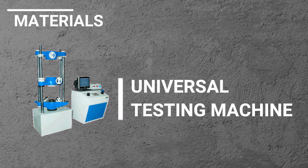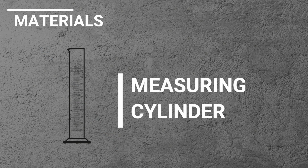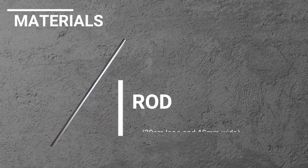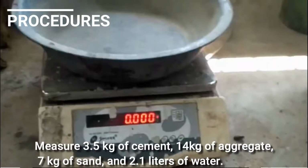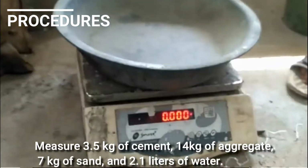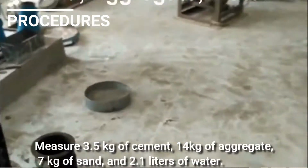The materials needed are the universal testing machine, cylindrical molds, specifically 100 mm in diameter and 300 mm in length, tamping rod, measuring cylinder, scoop and trowel, weighing balance, and two steel rods specifically 30 cm long and 16 mm wide. The first procedure is to measure 3.5 kilograms of cement, 14 kilograms of aggregate, 7 kilograms of sand, and 2.1 liters of water.